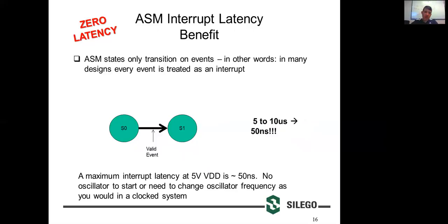So let's talk about what an interrupt is. An interrupt can happen when, say, a sensor detects a hot event and sends a signal to the microcontroller. That microcontroller might be in a very, very low power mode, let's say only a 32 kilohertz clock is running. It intercepts that signal at the next clock edge, so by definition you've already wasted 33 microseconds in that lower power mode. Then you wake up the interrupt service, change the clock speed, and handle all the code associated with the interrupt service routine. And 50 microseconds later, you've processed that interrupt, done whatever you need to do, and shut back down.